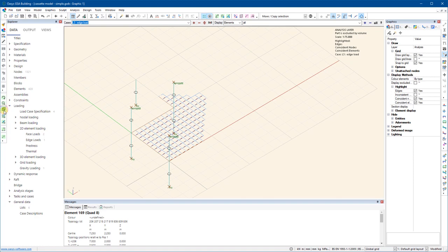If you go back and select the volume again, if you right click, you can delete either all volumes or the last volume. The benefit of this is you can do volumes in succession, and GSA remembers that, so you can step back a single step as opposed to deleting everything.